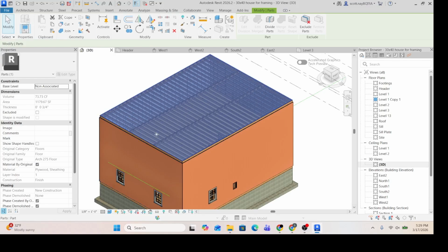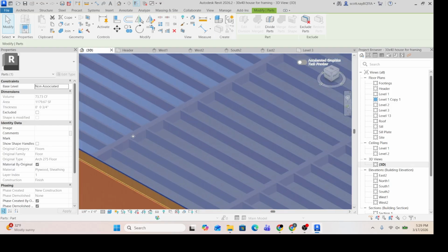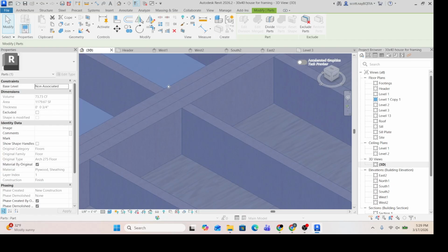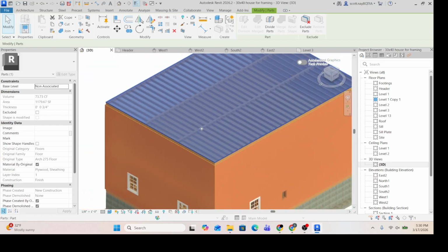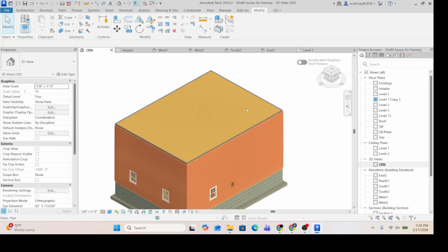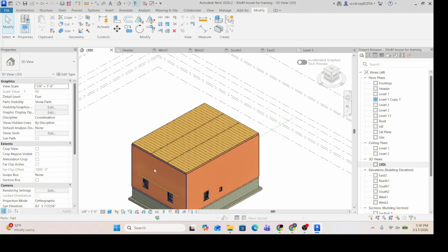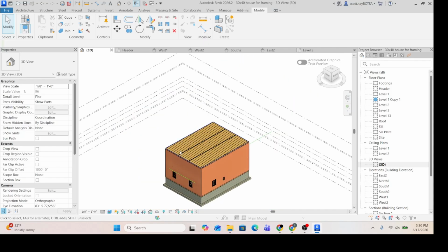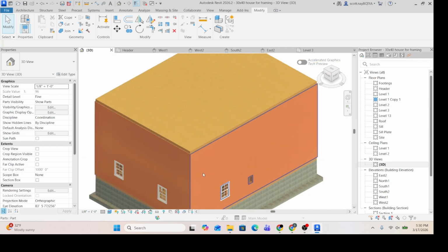Alright, so you can see I've done it again on this roof level. Just come in, done the triple 2x8s, split all these, and then use the multi-align tool. So what I'm going to do now is make a roof, and then use attach wall on the gable ends. And even though these have all been turned into parts, the parts will follow the wall.